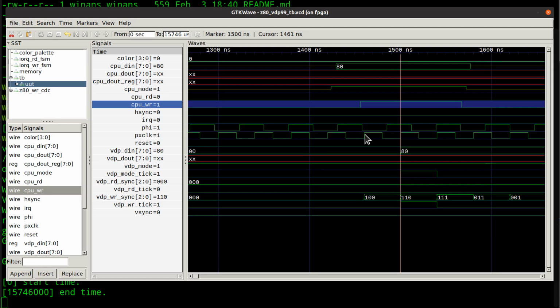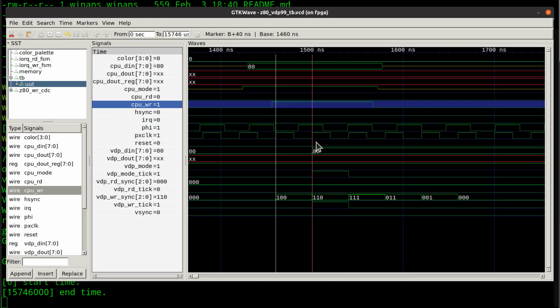This amount of time between these two is what? 40 nanoseconds. That's actually a long time. So if it wanders around and settles to a 0 or a 1, we should be fine by the time we get over here. So we're building a shift register, and I'm wasting time re-explaining how synchronizers work, but the short of it is, this is what we're looking at today, a type of synchronization that is a really basic one,